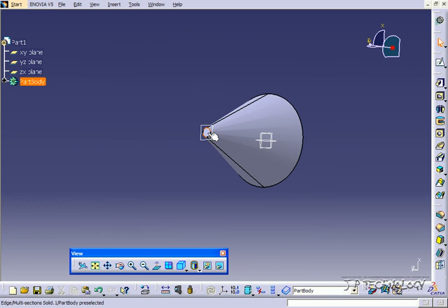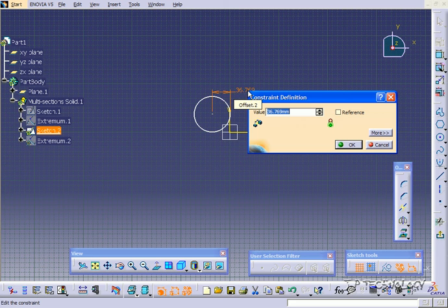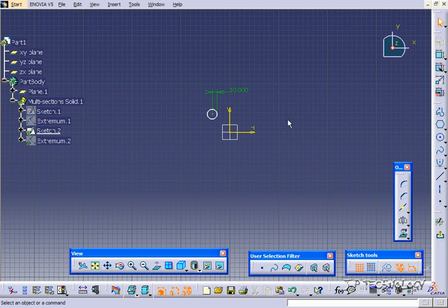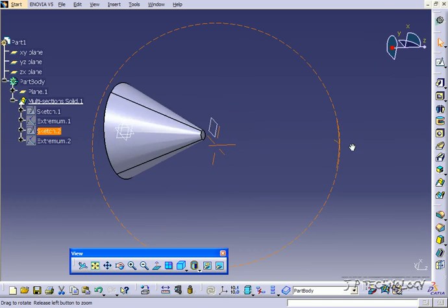Now let's play around with some of these sketches. Let's open up the multi-section there, click Sketch 2, and delete the sketch here, and let's move it around a little bit. So let's draw the circle up here and just drag it down a little bit and make it 20 millimeters again. So make it 10 radius, 20 mil in diameter. Go back out, and now you can see that it's kind of offset to the side there.